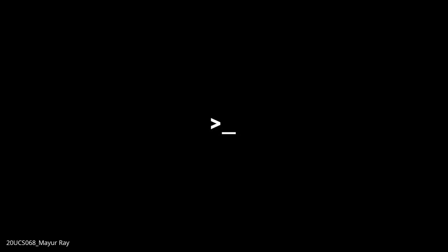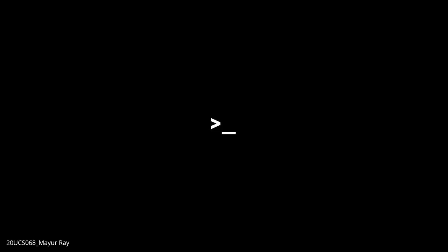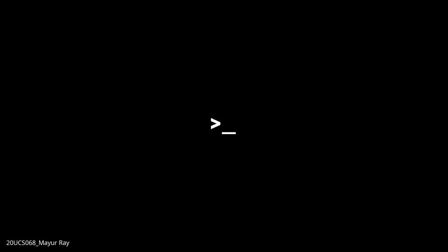Now you might be thinking, how is this actually working? We are clicking on my mobile phone, and how is it actually going to the LED? I won't bore you with the technical steps. Rather, I will just give you a small glimpse. Here I have shared some small code. On the left side, you can see that whenever we click the turn on button, it sends a command A over Bluetooth. And whenever we click the turn off button, it sends the command B to the Arduino or any microcontroller that you are using. Here, an ESP32 is being used.